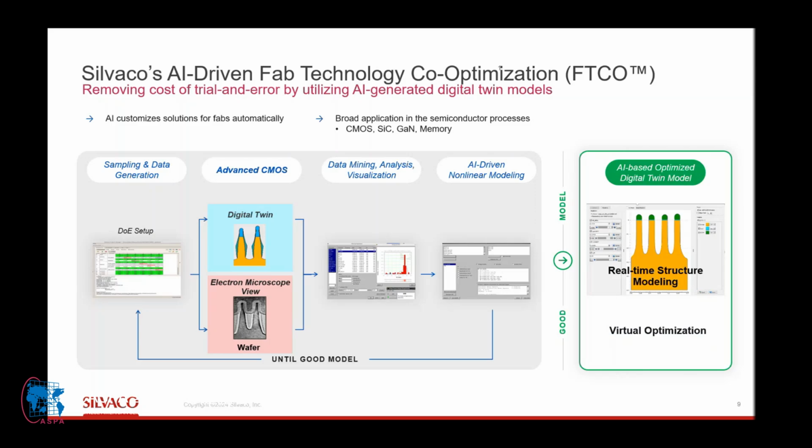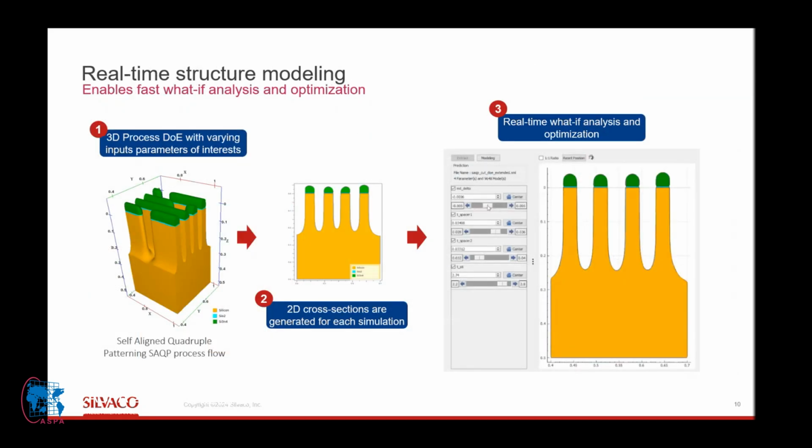So no one has seen this before. So it's unique, it's new, and we have announced it. Here's an example of it. If you look at this, people who are familiar with the process steps of devices, you'll see this is called shallow trench isolation, and there's a terminology called self-aligned quadruple patterning, which is basically by every time you do photolithography and repeat that step with different patterns, you can actually increase the resolution without having the accuracy of the lithography to be what you want the final results to be.